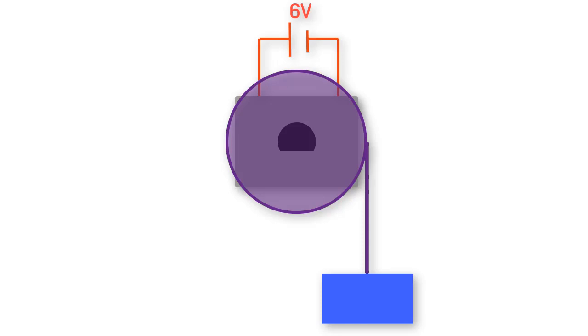I will probably break the motor because the power supply will try to push all 12 volts into the motor, and that's more voltage than the motor can take. But suppose I have a motor that needs 1 amp of current, and I hook up the motor to a power supply that provides 5 amps. The motor won't break. The motor will be fine because the motor will only pull the 1 amp it needs and will leave the other 4 amps behind.